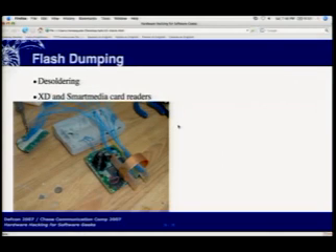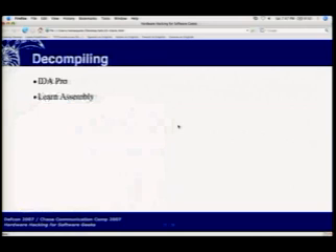The flash dumper thing I was talking about up there is for accessing more modern stuff, these 48-pin thin small outline package flash chips. It turns out that XD cards for cameras and smart media cards for cameras are basically NAND flash in a funny package. They're exactly the same interface, and you can use one of them to build a flash dumper that you can just clip onto the chip, and depending on the electrical characteristics of the board, dump the flash via a USB cable.